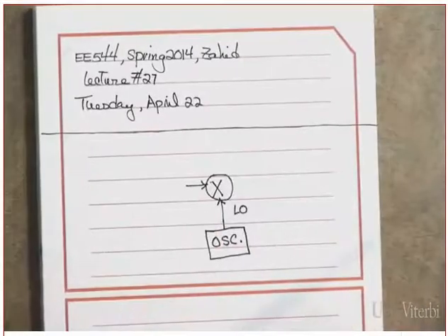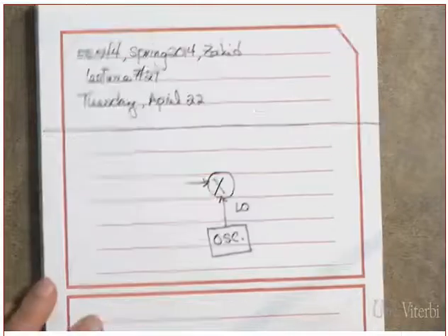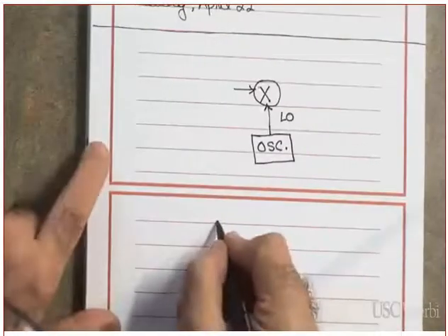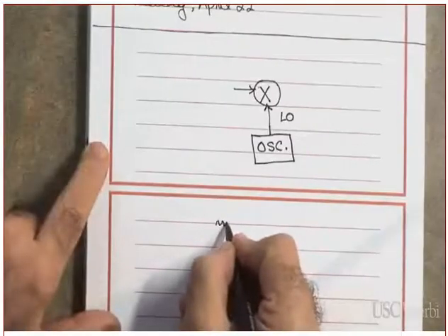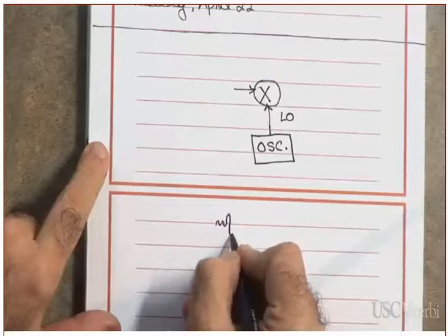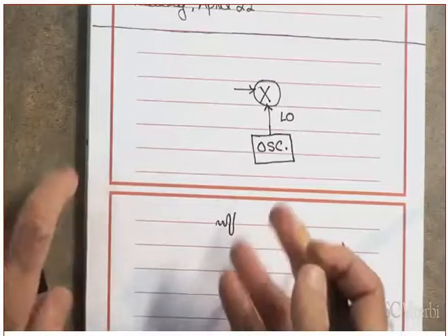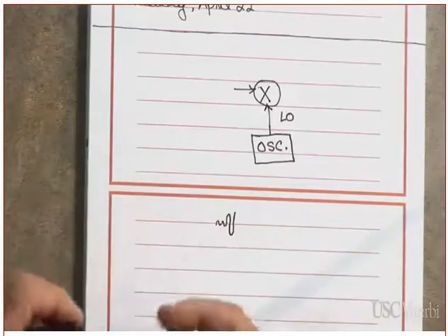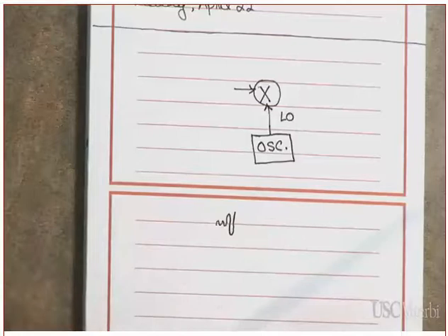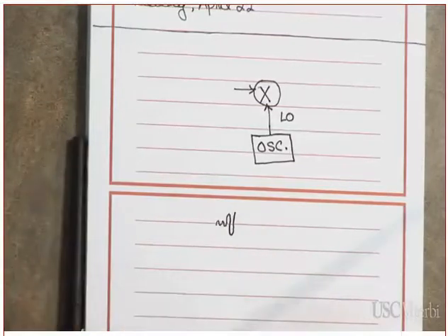Now, you might say, how does it build the oscillation by itself? Something triggers it, maybe just internal noise and some fluctuations from the power supply, and so on and so forth. It starts with certain fluctuations, but then it needs to build it up. How would it build it up? It builds it up through the use of an amplifier.